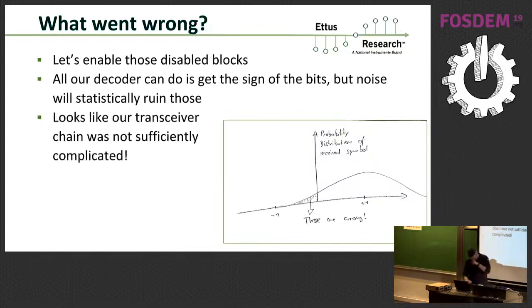That's my time. Now, if you look at this setup that I used, I'm transmitting +1, -1 bits, but I add noise. So I actually get this probability distribution of received symbols. And as soon as they move over here, I will interpret the +1 symbol as a -1 symbol, which is a bit error. This here is something I can actually trivially calculate for simple schemes like mine, using the Gaussian error function. So I can actually predict accurately my bit error rate.